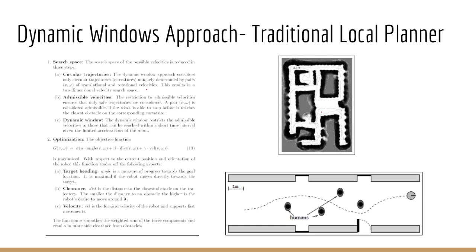We chose the dynamic windows approach planner as we found that other planners were not sufficient for our needs. RRT-based planners require a really good heuristic for finding a trajectory efficiently, and this heuristic might be hard to come up with. Pure optimization-based planning is also quite slow, and sinusoidal planners are not really practical besides doing parallel parking.